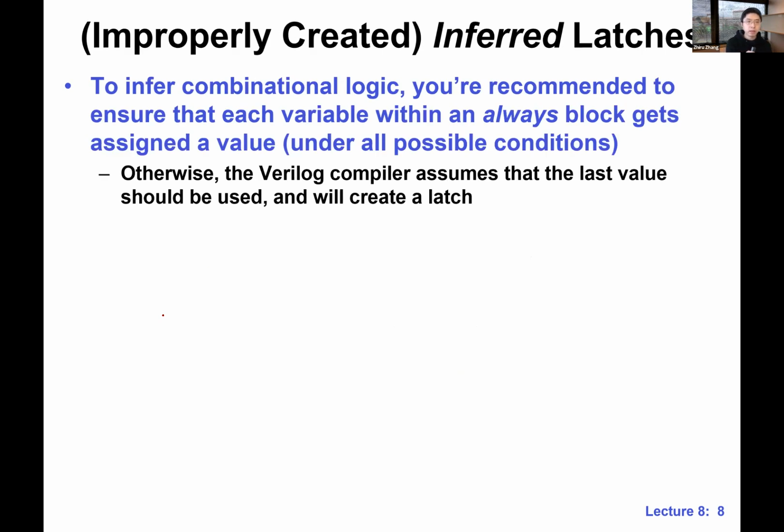And let's see an example. I think some of you are already running into this issue as part of lab 2. You might have seen this warning from Quartus saying that there's an inferred latch. We also want you to avoid creating inferred latches. What exactly does that mean?